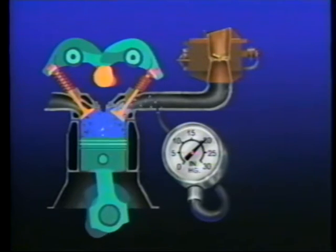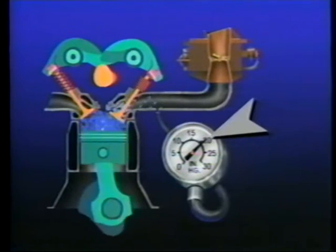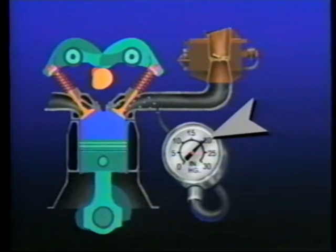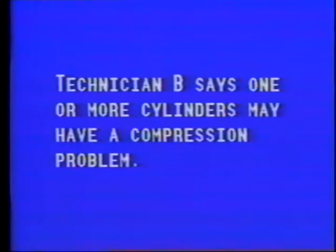The vacuum created by that cylinder would be less than the vacuum created by the other cylinders, so the vacuum gauge needle would drop regularly each time that cylinder began its intake stroke. Technician A's statement, then, is false. If the engine had an intake manifold vacuum leak, engine vacuum would be low, but the needle would be steady. Technician B's statement is true.